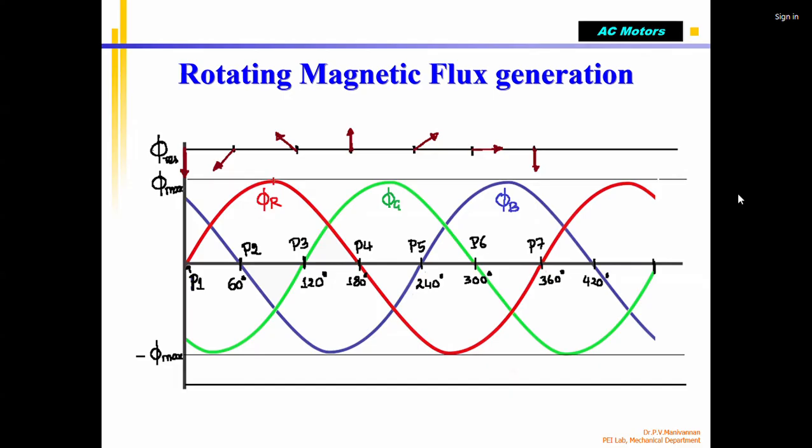Finally all three are going to interact on the rotor. So this is the resultant magnetic flux going to work on the rotor, but it also rotates. Correct? Within 360 degrees, it started at minus 90 degrees, then rotated like this, and finally came back to minus 90 degrees.